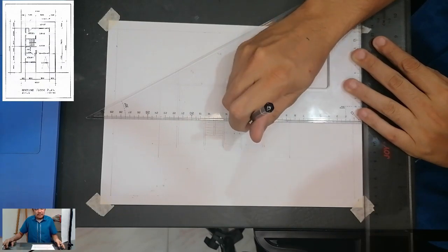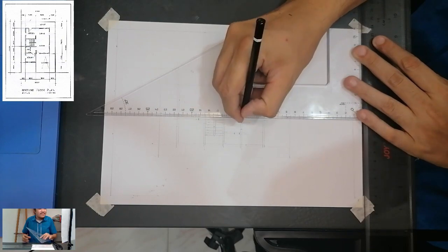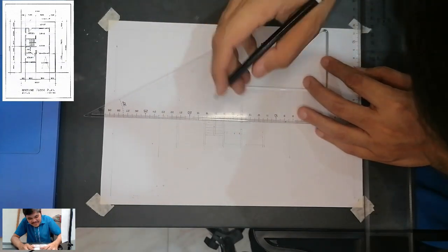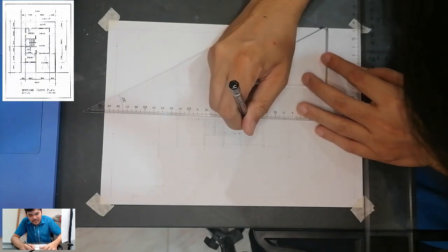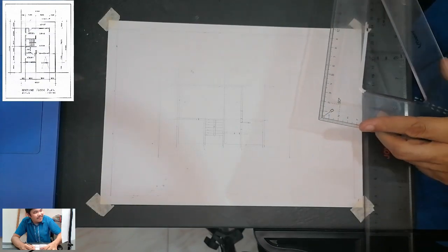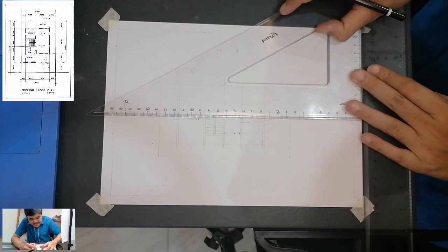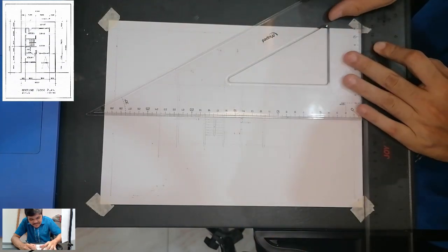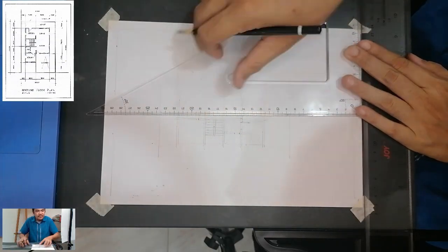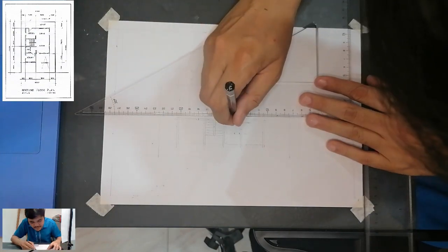Okay? So, dito ginagawa na natin ngayon class is creating yung mga door openings. For this one, makikita natin, alam niyo yung hamba. From the door jamb is 0.1 centimeter, or isang guhit lang sa ating ruler. And then, the door opening should be, for rooms, 0.8. Ibig sabihin, 8 guhit. In actual, it is 80 centimeter or 0.8 meters.